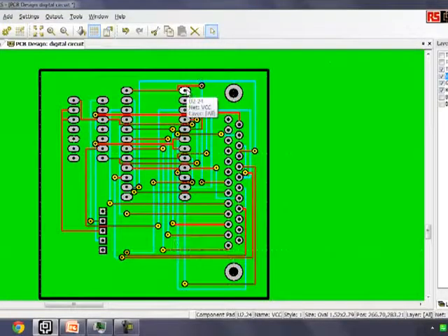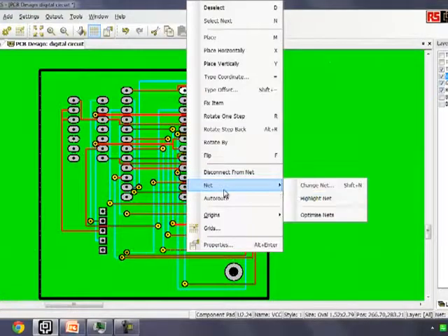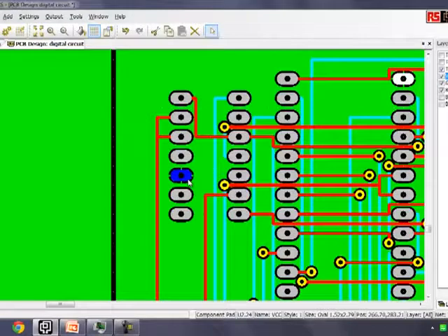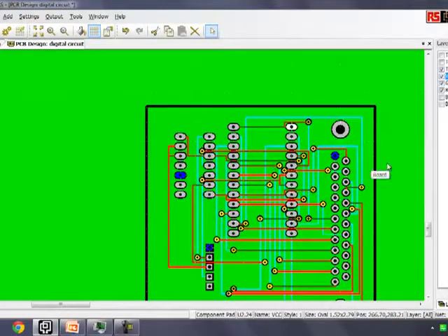So if I highlight this net, which we can see is VCC, a number of these pins have now turned blue, here, here, and here. The interesting thing is that you cannot see any connection or traces coming from these pins. All you see is that they are connected to the plane, which means they've been connected straight down into the board.